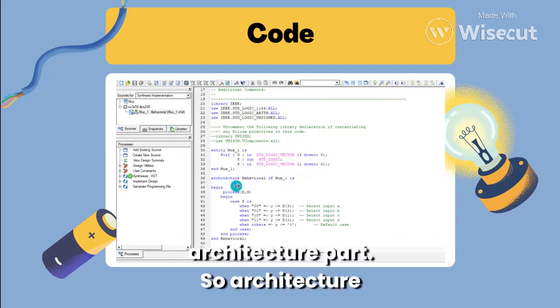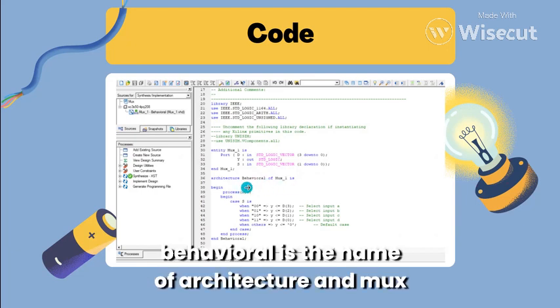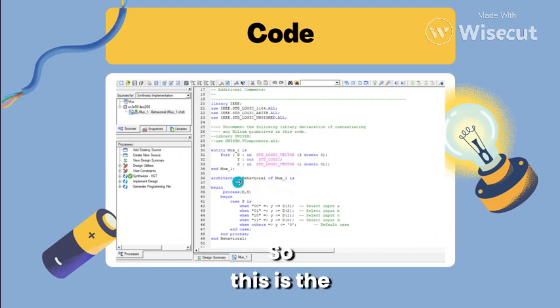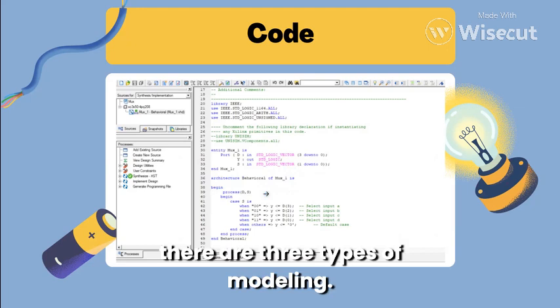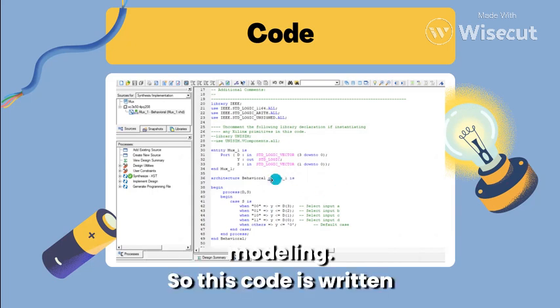So let's see the architecture part. Architecture behavioral of mux 1. In this line, behavioral is the name of the architecture and mux underscore 1 is the name of the entity. So this is the architecture part. There are three types of modeling. Among them, we are using the behavioral type of modeling.